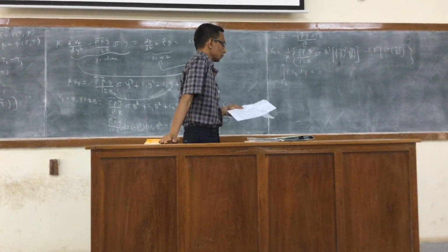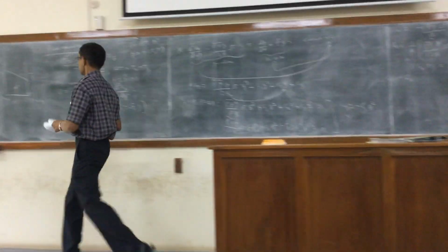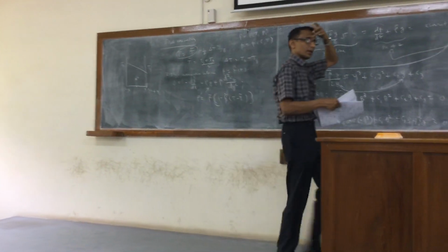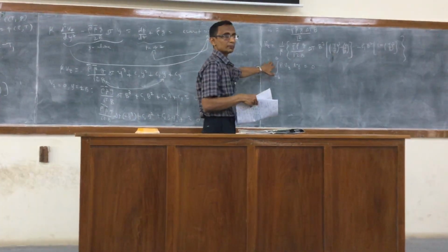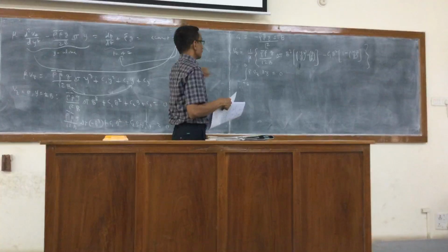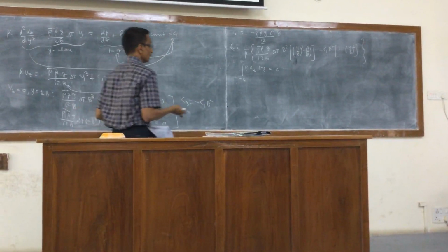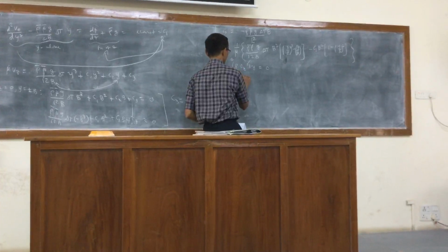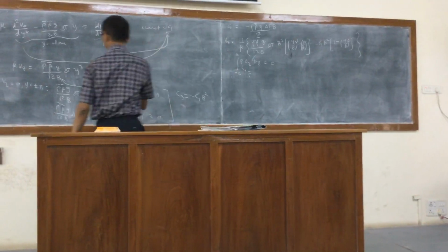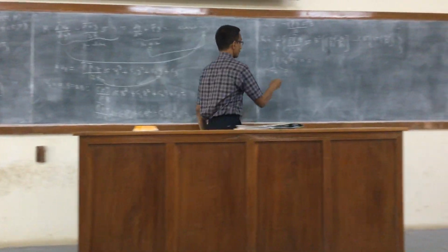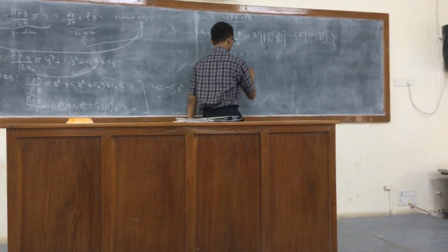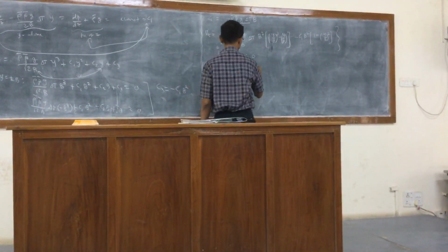Of course, another dimension would be, the mass flow is in the z and then also in the x direction. That integral will just cancel. You get the breadth of the plane, right? It's not going to contribute. You get a net effect of that. So, if I substitute, effectively I have v_z here, and for rho I have to substitute rho bar times 1 minus beta bar times T minus T bar.